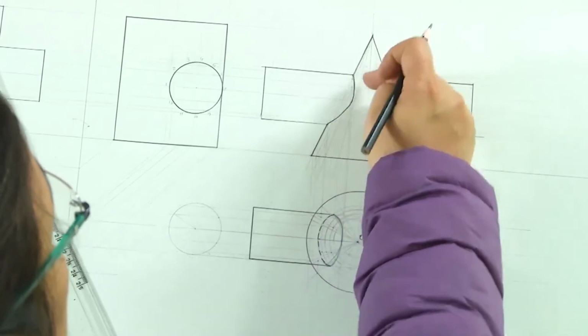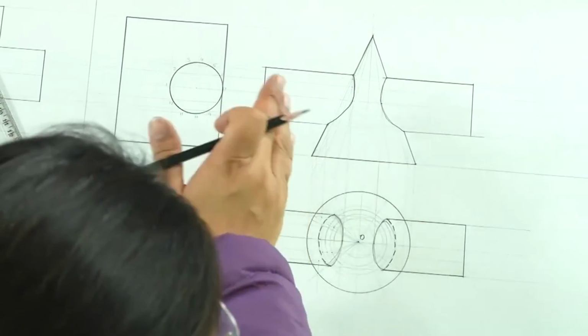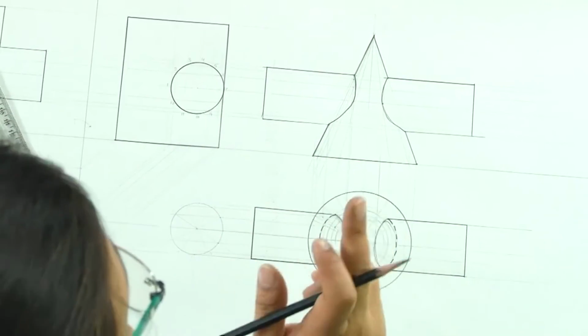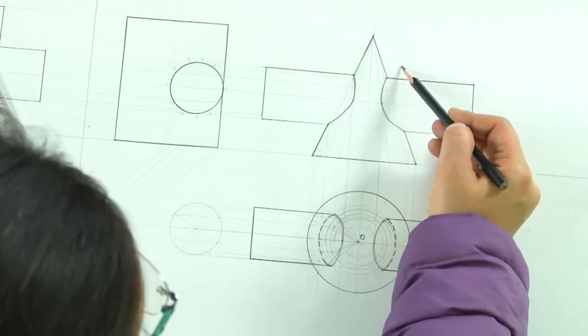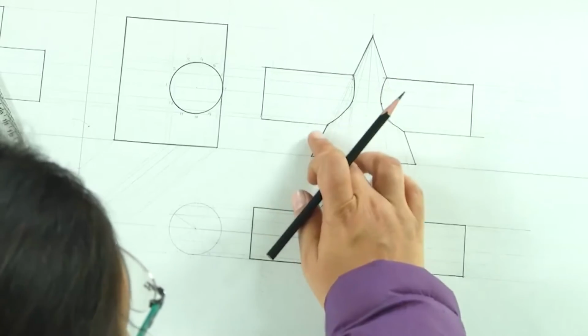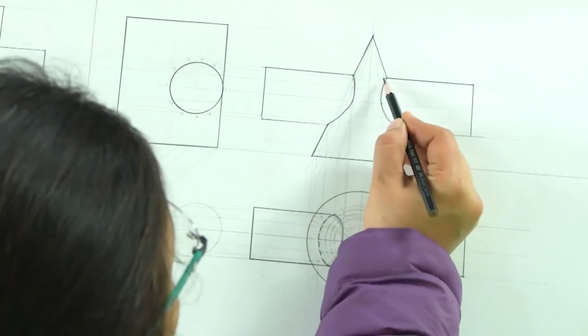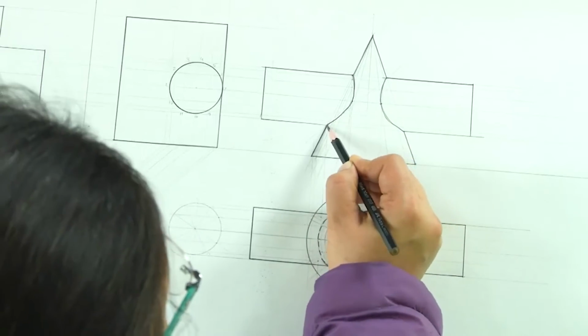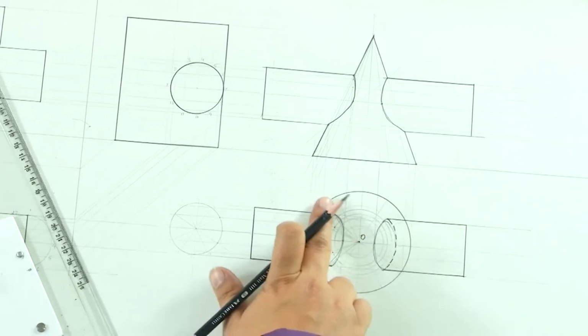This surface is also curving and inclined, and this surface is also a curved surface. So, we will never get a straight point. If this cone was being intersected by a straight plane like this, we would have arrived at an ellipse, but it is not happening that way. It is getting cut at different heights and at different widths, which is what will yield a very skewed shape here.